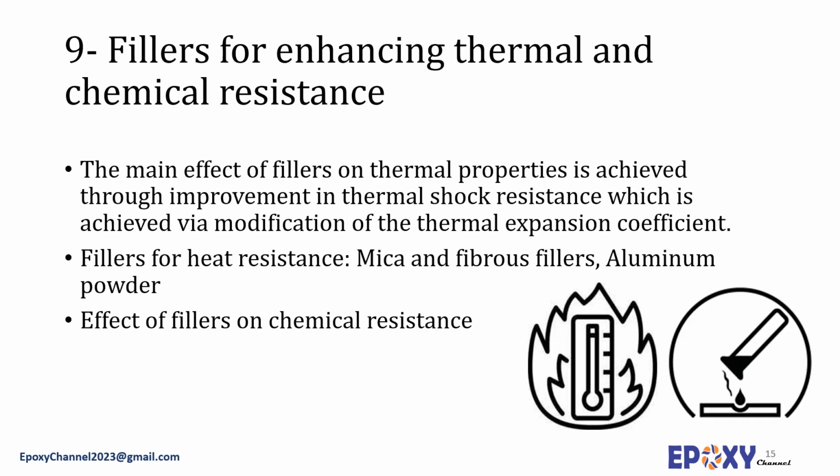Fillers improve the thermal properties of the cured epoxy formulation by bulk displacement of the organic component. This reduces long-term shrinkage and thermally induced weight loss. However, the glass transition temperature is not significantly affected and in some cases may be lowered. The main effect of fillers on thermal properties is achieved through improvement in thermal shock resistance, which is achieved via modification of the thermal expansion coefficient.